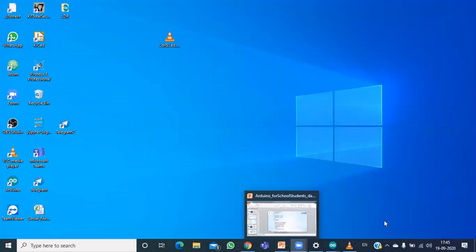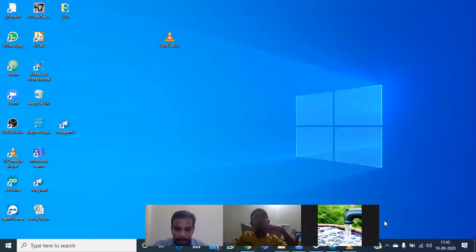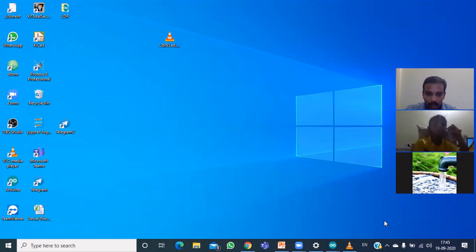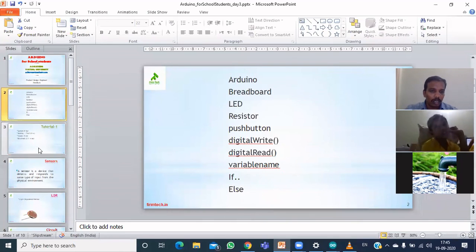So once again, we have discussed Arduino board, breadboard, LED, resistor, push button, digital write, digital read, variable name, if else, and today we have discussed analog read, and serial monitor, that is Serial.begin(9600), as well as Serial.println.